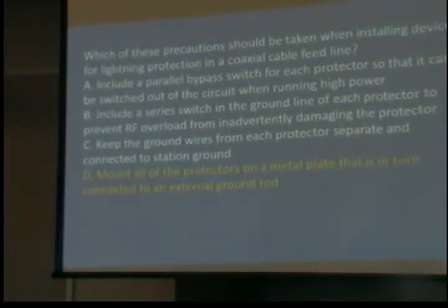The 8-foot ground stake costs $6 at Lowe's. The clamp for it costs $1.75, I believe. And a piece of number 4 wire to go down, maybe $1. And if you can use a pair of pliers, a screwdriver, and a hammer, you can put it in.